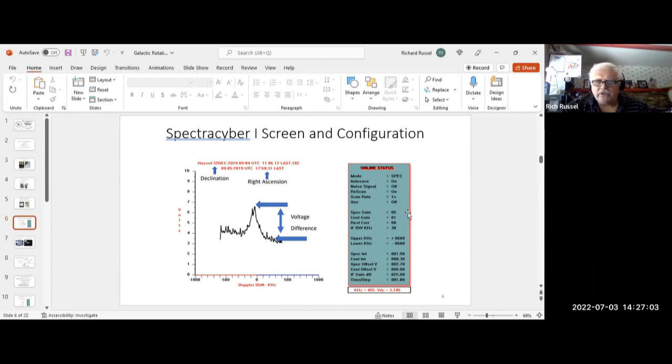I could set the range for how many kilohertz plus or minus. The 0 you set in the data is the actual frequency. So I put the hydrogen line, 1420.4057 megahertz, as 0, but there's a rest correction there.